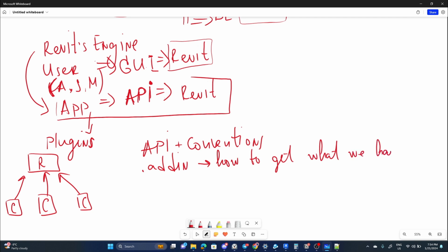That's the main idea that this add-in file answers. And then somewhere you have your own files, and we saw that those should probably have the DLL extension, if you go back and see the moment where I showed you what Revit actually consists of, that it's just a bunch of files at the end of the day.